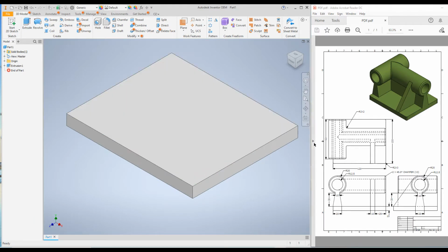Now it is the second feature. This part, if we follow the right sequence, is not a difficult part. So the next feature should be this extrusion, the T-shape extrusion with this slanted face. How are we going to do that? First we will create straight extrusion, and next use chamfer command to make this slanted surface.